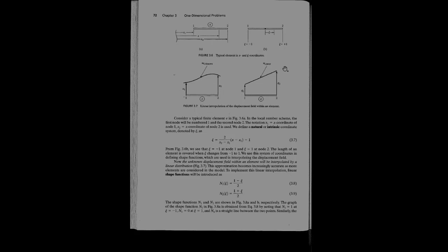You'll see the shape functions down in the book for the quadratic elements, but I want you to actually go and plot them in SymPy yourself. So just as a quick example. In essence, what it boils down to is we write the displacement field as a collection of the N's, the N vector times the unknown q's. So this is u and q, what you've seen before.